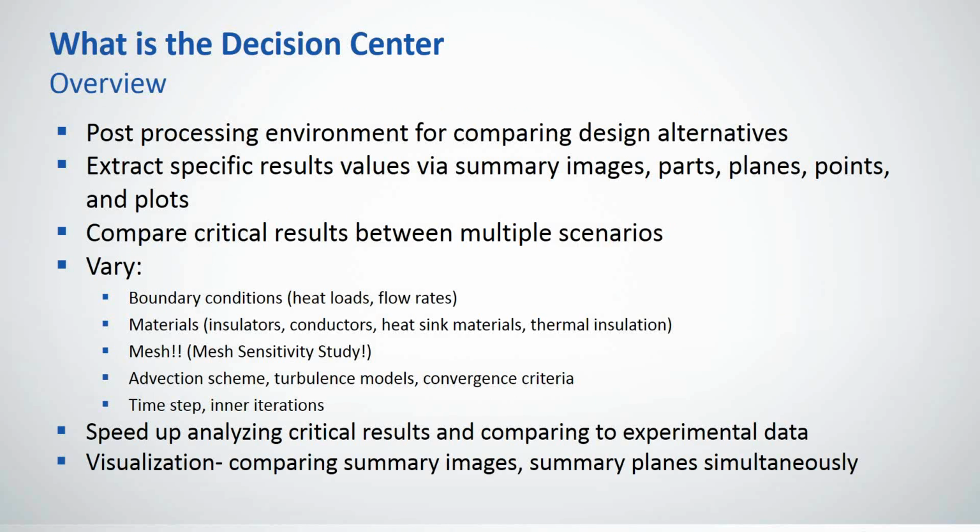So what is the Decision Center? Like I said, it's really a way to extract results extremely fast and just get answers to the questions you have. So instead of going into every design scenario, which you could have 10 or more at times, you just have to go through a workflow once: you add a summary, add a plane, add some points for an XY plot, and then you just hit make summary, and the workflow will be done for all your scenarios and, if possible, all your designs.